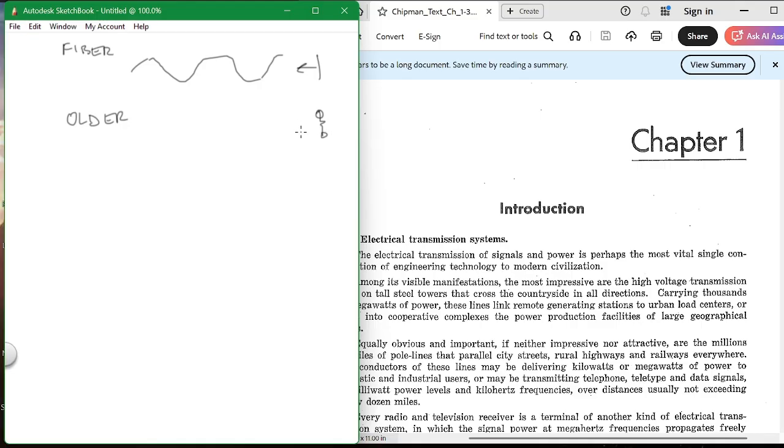So that's an aside about something that you don't have to worry about today, and why, when we use cables today, we use what we call UTP, unshielded twisted pair. And why can we do that at high speeds? Because the twist rates are all different for the four pair. You have four pair in there, and if you take it apart and look at them, they're at a different twist rate.